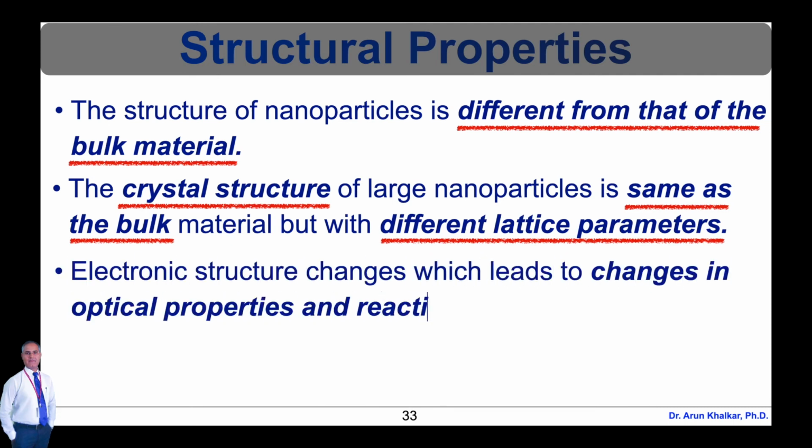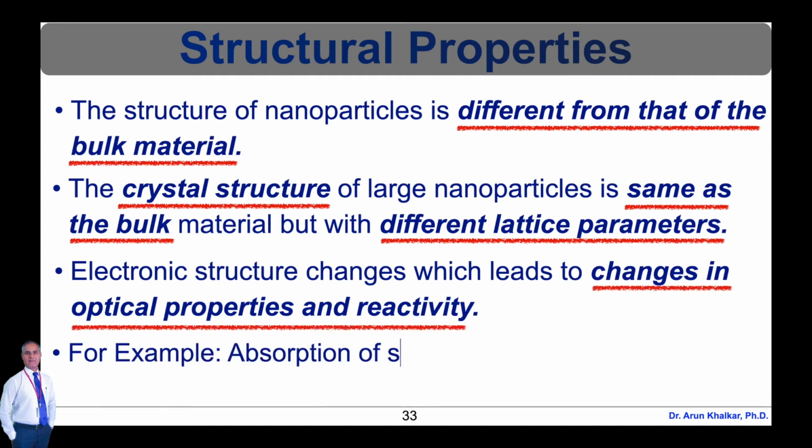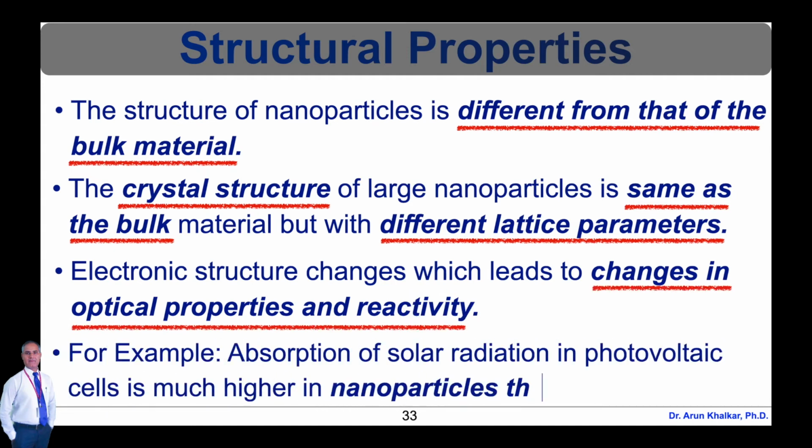Nanoparticles exhibit enhanced diffusion at elevated temperatures due to their high surface area to volume ratio. This property of nanoparticles allows sintering to take place at lower temperatures than in the case of larger particles. While this diffusion property exhibited by nanoparticles may not affect the density of the product, it can lead to agglomeration.